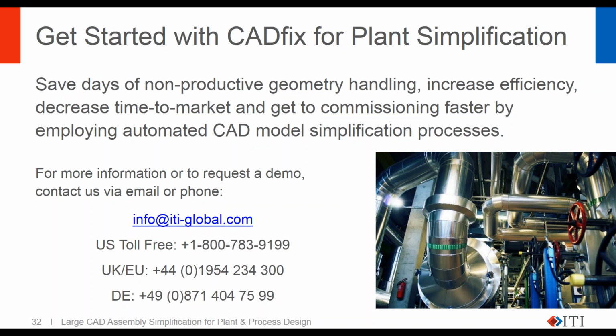But we have got some reverse engineering tools as well to reverse engineer that tessellation into a regular CAD solid, but that is very, very dependent upon the quality of the point cloud, the quality of the resulting tessellation, and whether or not there are clearly identifiable feature lines in the CAD model. Great. So I would say point clouds is one of the things we're researching for the future.